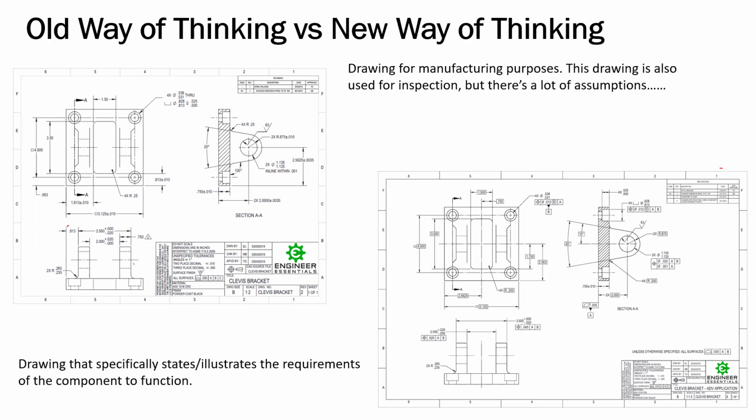And then, on the side of inspection, really deep down, we're creating an inspection document with this drawing, right? It's supposed to convey our design intent. It's supposed to have the functional requirements of the component back to its assembly environment. But truly, at the end of the line, this is going to be an inspection document, and this is telling quality exactly how to inspect it.